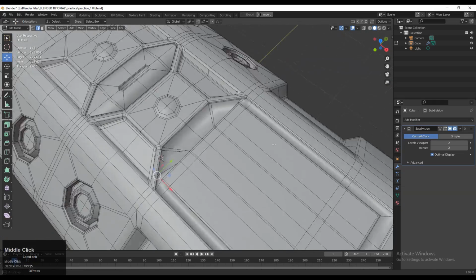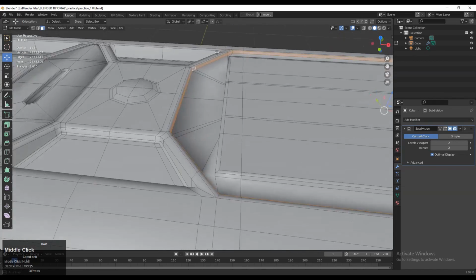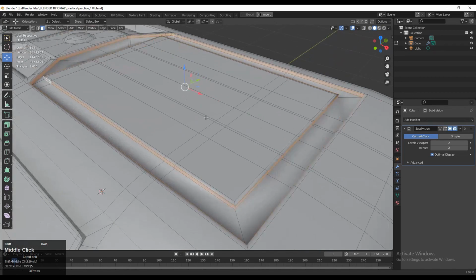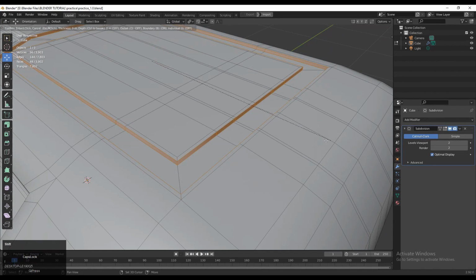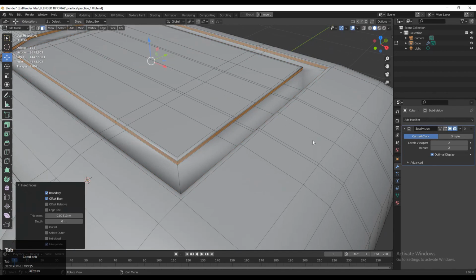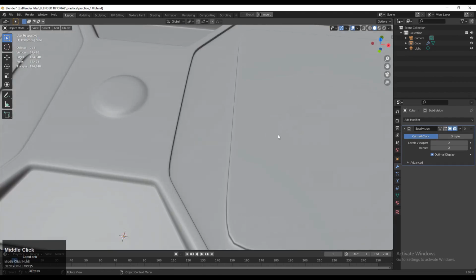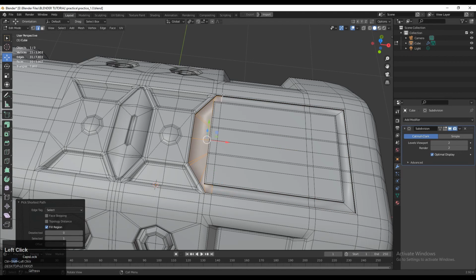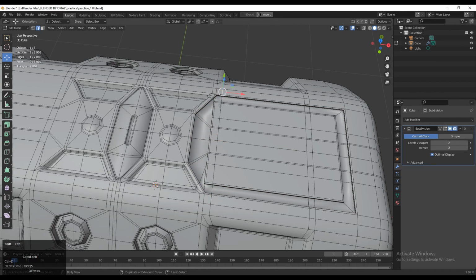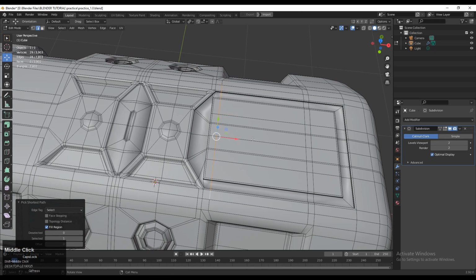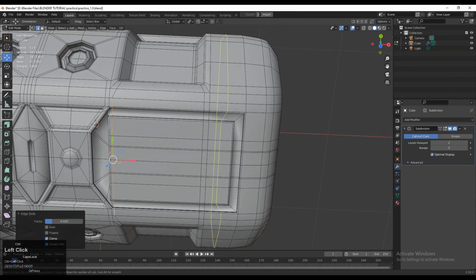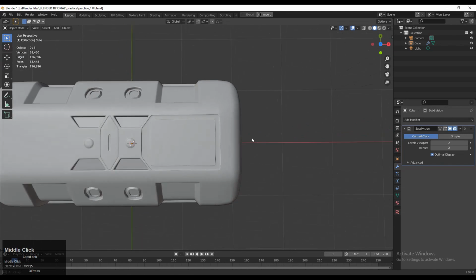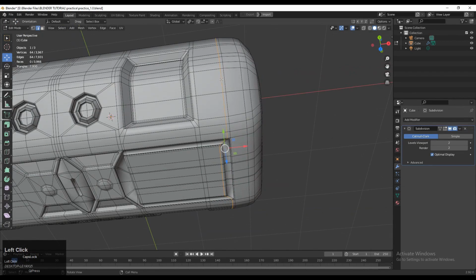Use the simple methods to create an amazing design. If I select these face loops, you can press Alt and select them, Alt Shift select them, and then press I for the insert operation. If you use the insert operation, we will get a little bit of weird result. If your topology is right for the depth of that extrude operation, then you won't get those weird results. And if there are more subdivisions, then you won't get those weird results.